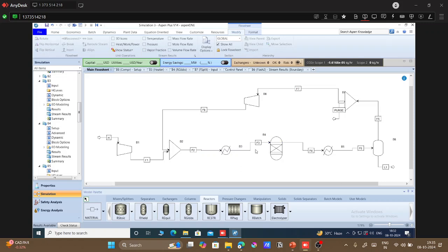As we had discussed, the Gibbs reactor uses a Gibbs free energy calculation to find the equilibrium composition, while for CSTR, PFR, and batch reactors we need kinetic parameters. Similarly for yield and equilibrium reactors we need to provide some reaction or composition that we have to get, while this calculates the conversion based on the Gibbs free energy data.